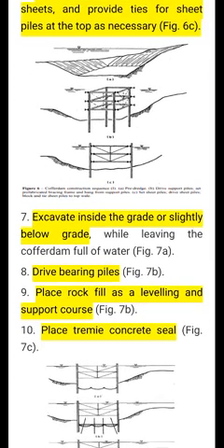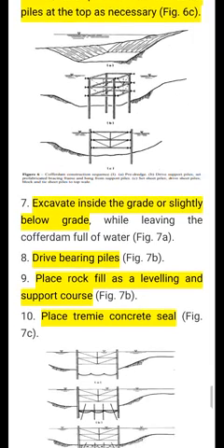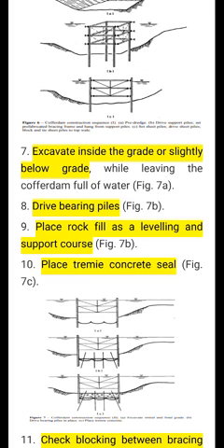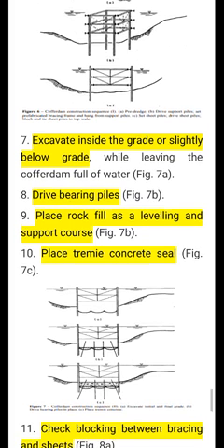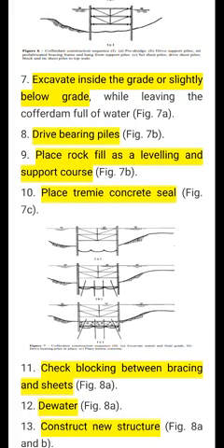The figure itself shows how it could be. Now the seventh step will be excavation inside to grade or slightly below grade while leaving the cofferdam full of water.